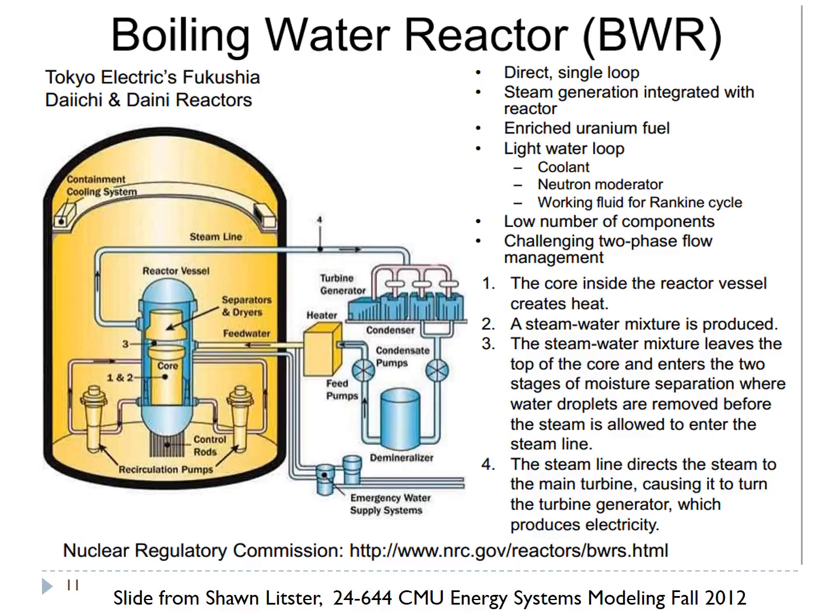Okay, so let's talk a little bit. Here's a process flow diagram for the boiling water reactor, such as at the Fukushima Daiichi reactors. In this case, as I said before, the actual working fluid for the Rankine cycle goes into the core and boils. The key thing here is less equipment. However, we now have to deal with boiling inside the core, and that can often be less safe than what we're going to show in the next slide, which is the pressurized water reactors.